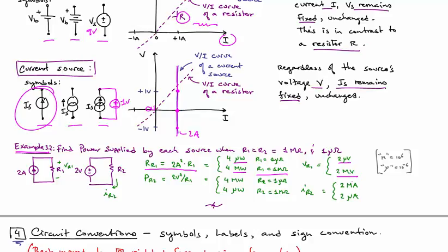Okay. The same, or similarly, is the case for the second resistor. Here we have a voltage source across it, so I've written the power to the resistor as V squared over R. So now we have 4 over R. And again, if we have 1 microohm versus 1 megohm, we have very different power. Now notice that they're flipped. In the first case, if you have a very small resistance with the current source, the source doesn't have to do any work, because asymptotically, a short there means no voltage, and therefore no VI product.